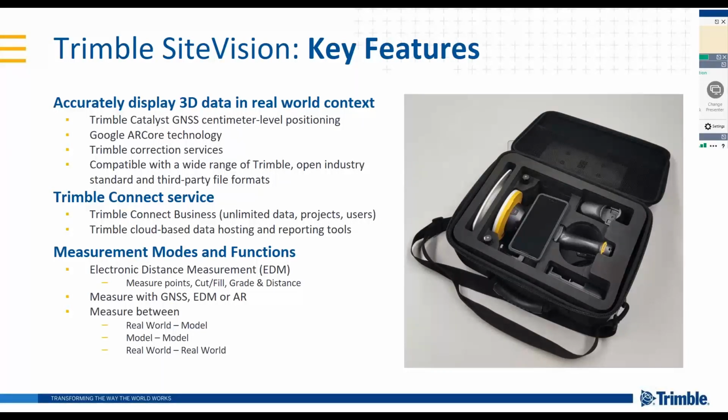You have that capability to measure points, put in codes, put in antenna heights, and then store these types of measurements. You can also use the ARCore itself for taking measurements to a model. So in this case, you can measure between the real world and a model. You can measure between model and model, and you can also measure between the real world and the real world.